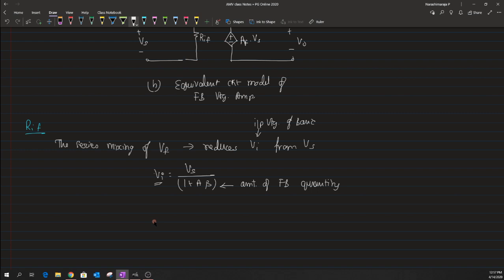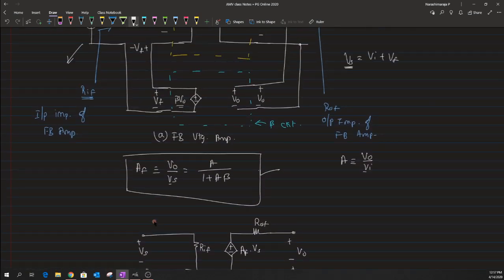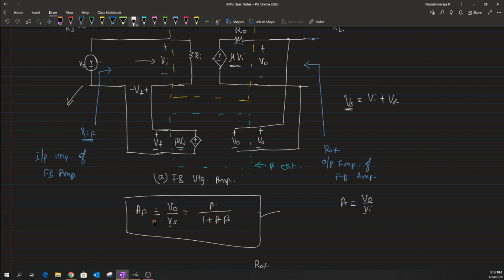So now, because of this reduction, in case I just want to measure the input impedance, what I can do is ensure the current flow through this particular circuit, labeled in, let me use some color, yeah, I'll use the green one. So we know that the current that flows into the circuit is taken as Ii, and we also know that the ratio of this Vs with Ii will give us the input impedance of this feedback amplifier, which is RIF. Okay. So with that, let us try to have a discussion, clear.